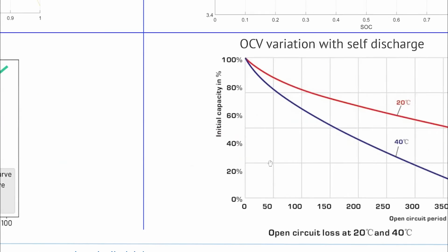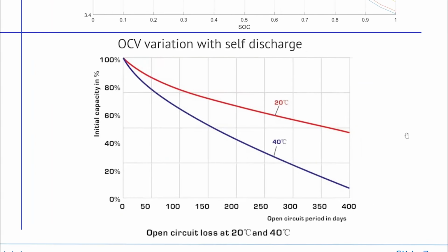Then we have self discharge. You can see here the y-axis is in terms of capacity, but it also applies to voltage, because when you store a cell over a very long period of time, you can see here it is crossing 1 year in storage. When you store them without any activity, the open circuit voltage also starts to drop, or you can say there is some irreversible loss in voltage of the cell. If you also change your temperature, say you store at 25 and then store another battery at 45 or 50 degrees, you will notice that the rate of degradation also changes along with it.